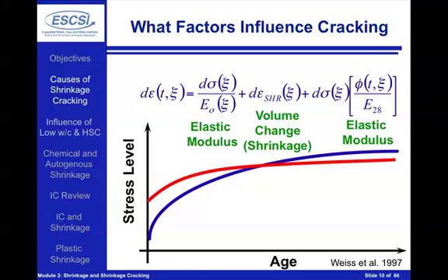What we can see here is the elastic modulus plays a large role in this problem. With a higher elastic modulus, actually leading to higher stresses developing in the system. What we'll see in Module 4 is that internally cured concrete will actually result in a lower modulus. It'll enable the concrete to be stretched over a longer distance, developing lower stresses in the overall system, and therefore lower elastic modulus of the internally cured concrete is actually beneficial to help reducing the potential for cracking.